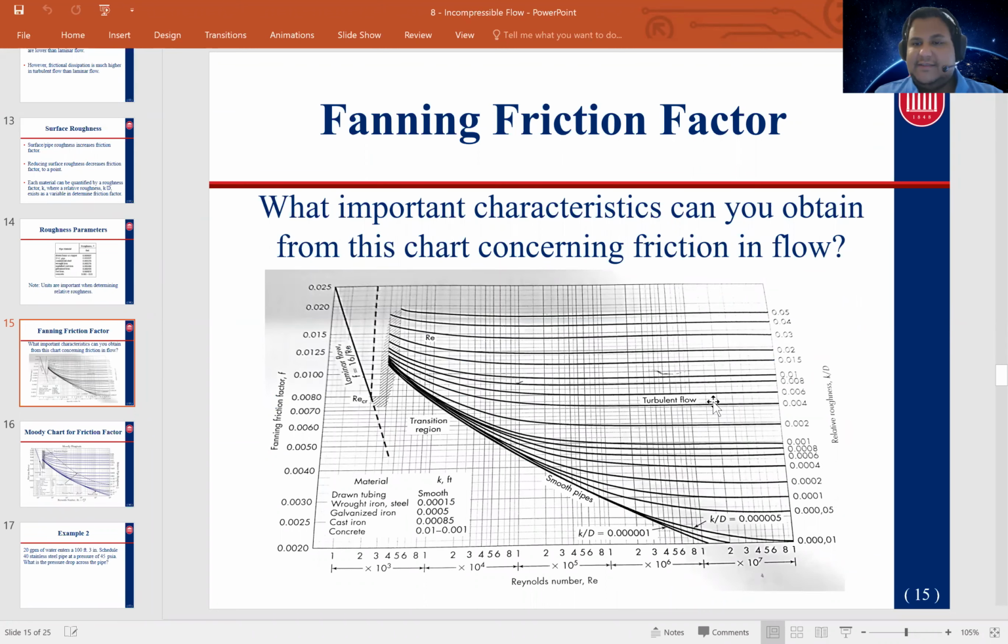So if you get to this region here, and a lot of times you can even consider it just about 2 million and above, the friction factor isn't going to change appreciably with manipulating your flow rate, provided you're not decreasing it. And so in that instance, I can say, well, assuming a high Reynolds number, f is constant.